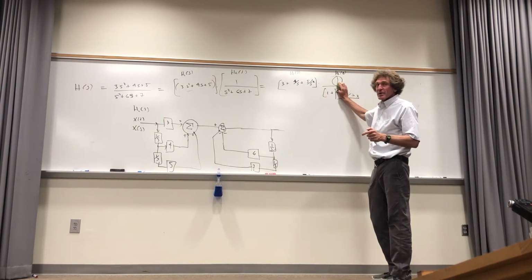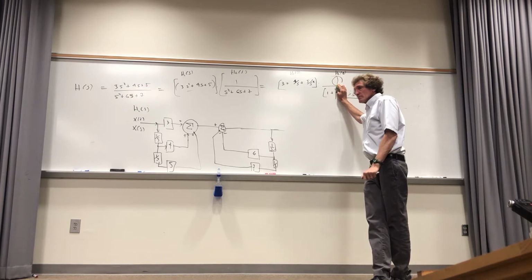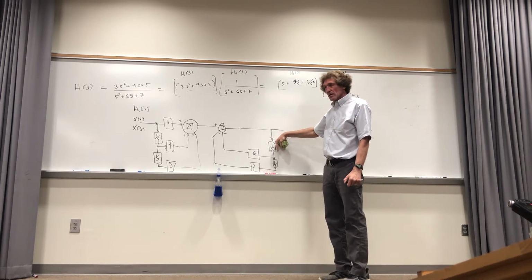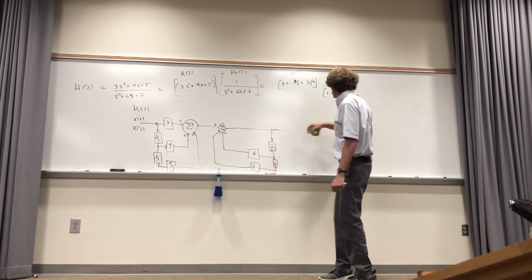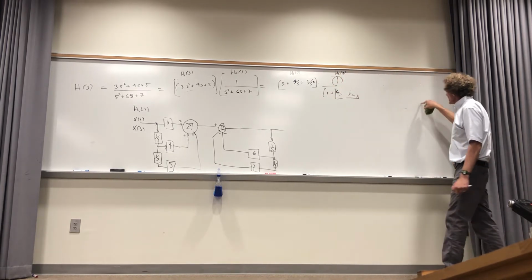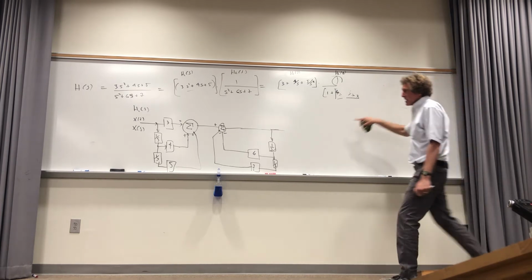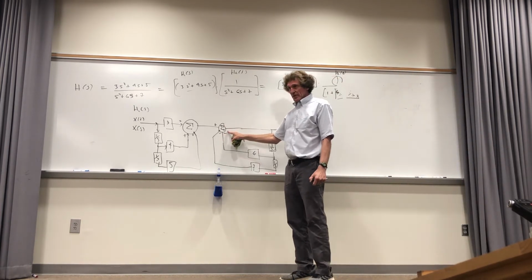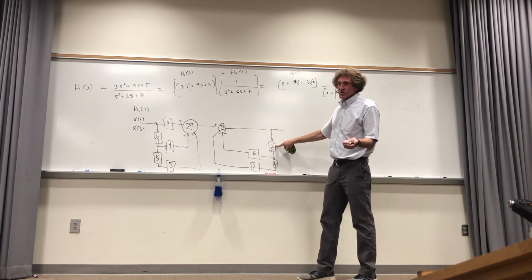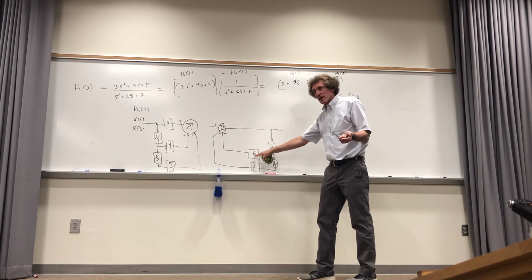One other thing too, the reverse of what we're doing, oh yes, sir. I just want to make sure I understand the concept. So when it goes straight down, that's when you're using the variables? Well, this is just a 1 over S term, right? Right. And see, I'm trying to realize this function right over here, right? And I showed you the block diagram, A and beta, right? The negative. So here's the summer that takes the negative values, right? And then over here, what I need to get is a 1 over S for starters. Then I have to multiply by 6 that value.